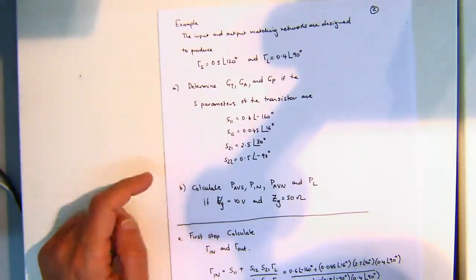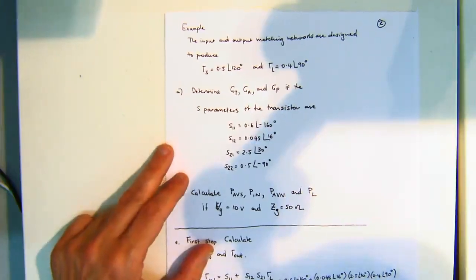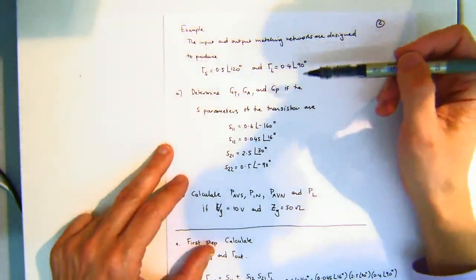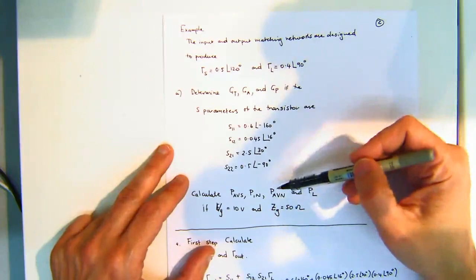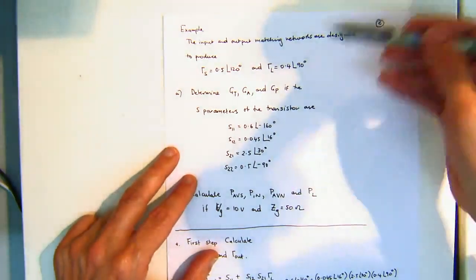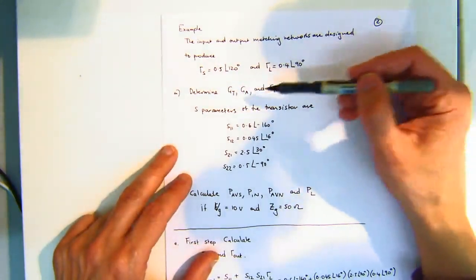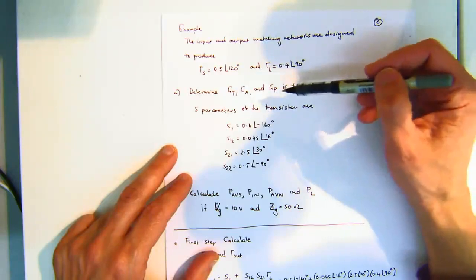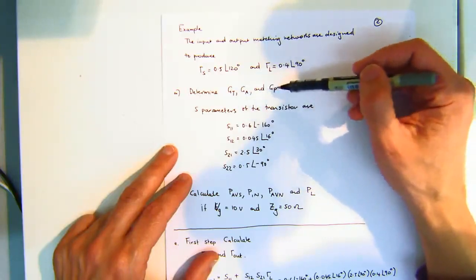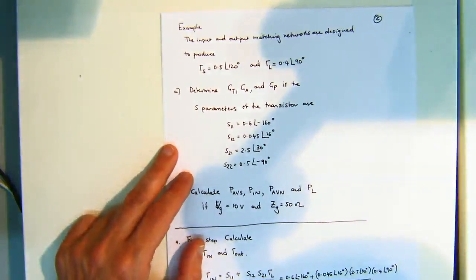All right, that's what we did. Then we went through a simple calculation which hid a lot of complexity, but nonetheless, let's assume that we're given this particular transistor, it has the following scattering parameters, which is essentially, I've biased it some way, and what I'm asking you to work out is the transducer gain, available power gain, and the total gain.